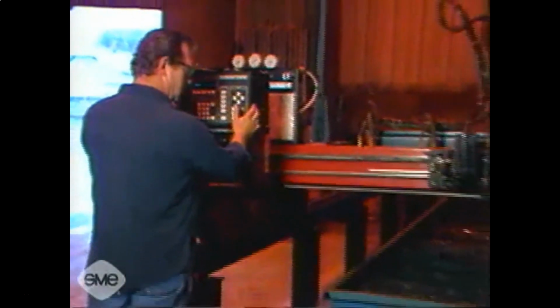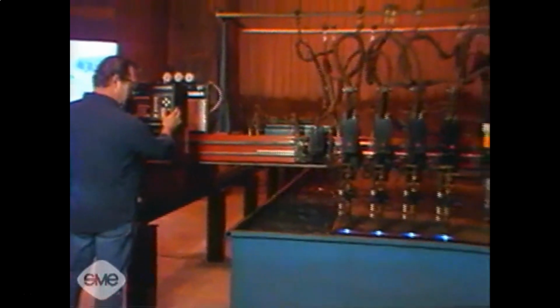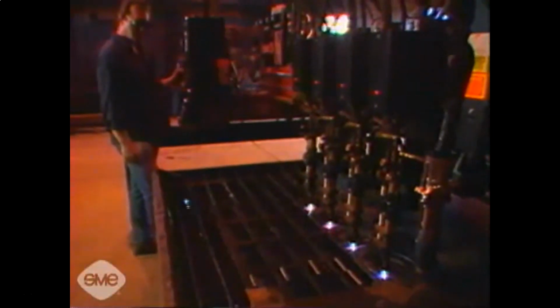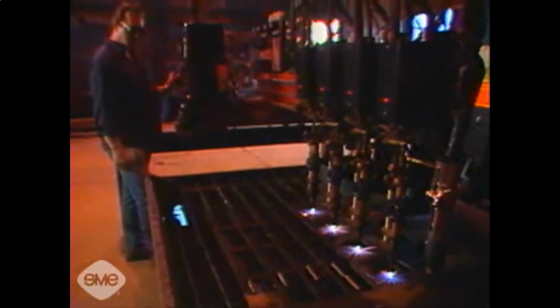Once the starting area reaches the kindling temperature, the operator turns on the jet of compressed cutting oxygen. The oxygen streams from the torch tip into the glowing red preheated metal, causing a fast combustion reaction between the steel and the oxygen. The resulting molten material, or slag, is blown through the metal by the stream of cutting oxygen. This exposes fresh metal to the cutting stream.